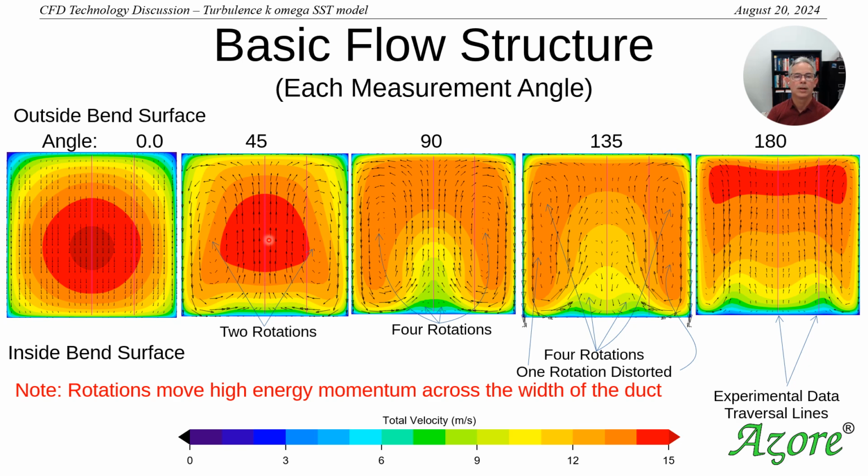The inertia of the fluid has traveled to the outside of the duct, and because of continuity, it needs to go somewhere, so it begins forming these counter-rotating vortices. And you can maybe interpret that we are developing a tube that goes around our elbow. Right here, this is one tube, and there's a secondary tube of these rotations.